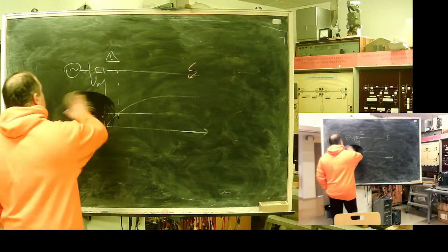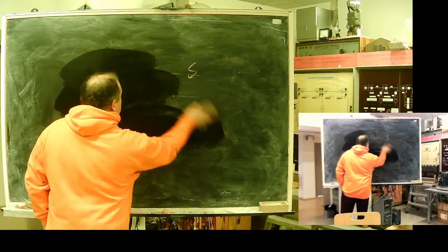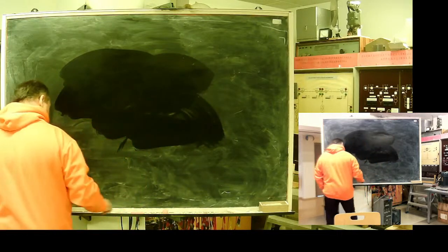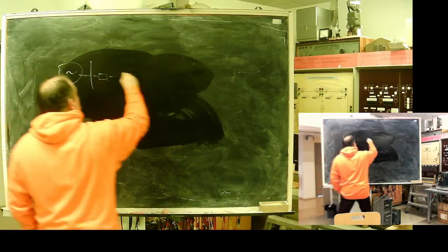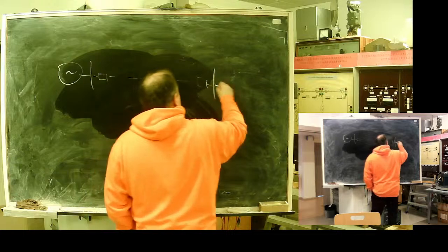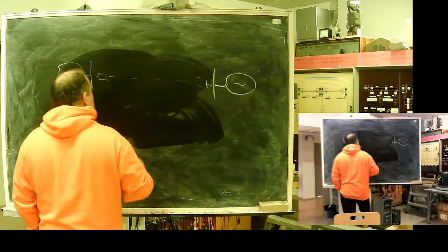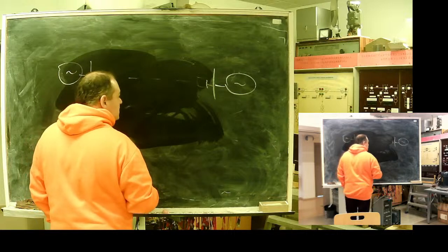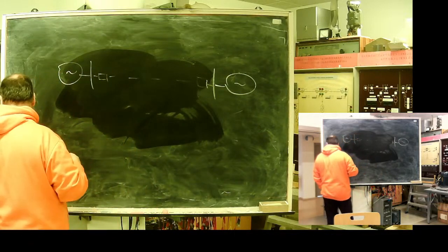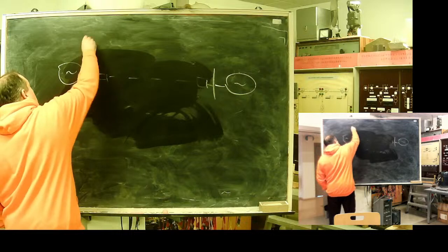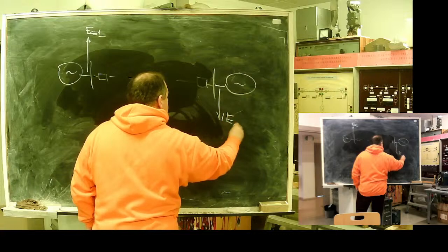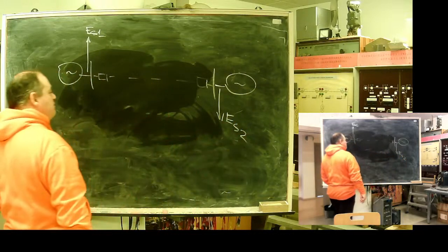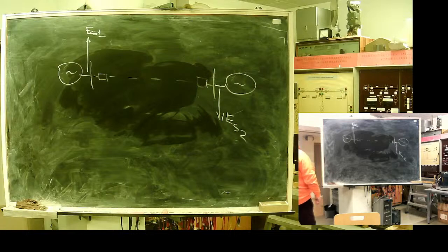Also, I will repeat, distance protections are vulnerable to power swings. Let's say some connection between systems. In case of a serious problem, the loss of synchronicity, we have a severe condition in our system, lost synchronicity.